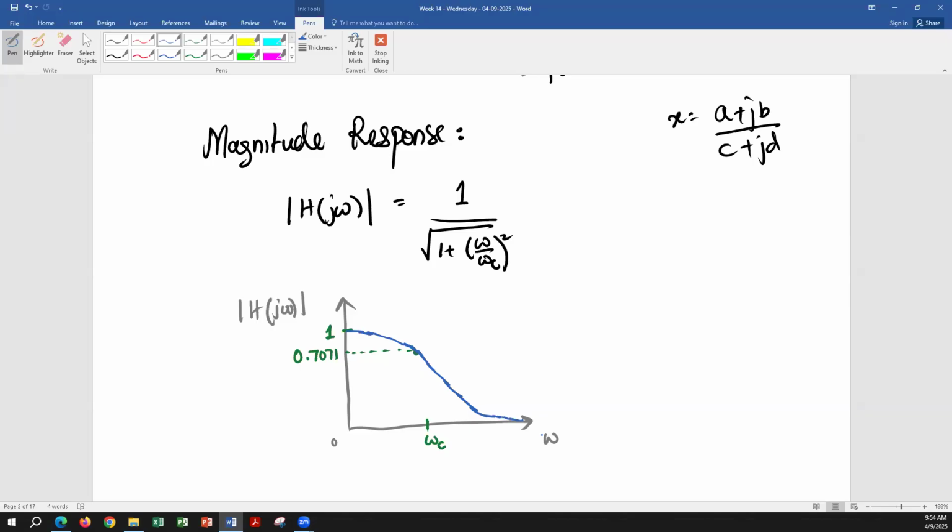So in general, filter responses are plotted this way, as well as when you're doing the simulation. And simulation in PSpice is done using what? Remember anyone? We did that in software class. What type of simulation do we use when you're doing frequency simulation in PSpice? Yeah, all of you took PSpice with me. AC sweep. So anytime you are performing the frequency or noise analysis, when you go to PSpice, it says noise or frequency. You perform AC sweep analysis, remember that.